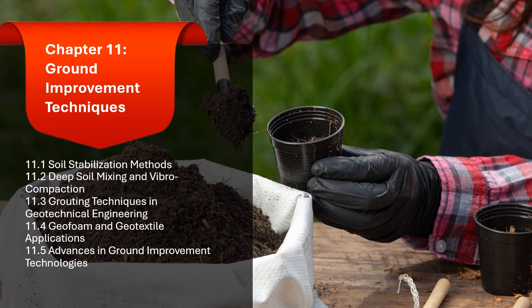1.3.3.1 Foundation improvement. Grouting can be used to enhance the load-bearing capacity and reduce the settlement of foundations. It is commonly used for the improvement of weak or unstable soils beneath existing or proposed foundations. Grouting methods such as permeation or compaction grouting help increase soil strength, reduce settlement, and prevent structural damage.